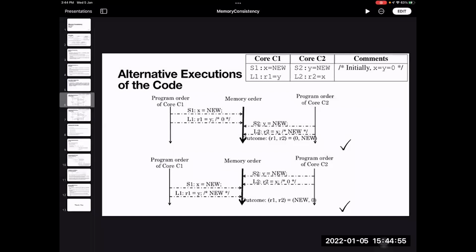Yeah. So just one more thing. Since we are disabling the store buffers, basically we are not dynamically scheduling the memory instructions. We are only going in program order. Even if there is a store operation and a following independent load, we just go ahead with the normal order. Okay, but that is very rigid, right? Yeah, that's where I was coming.